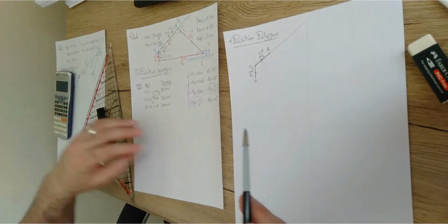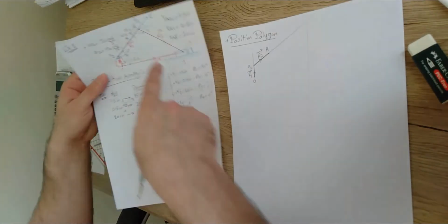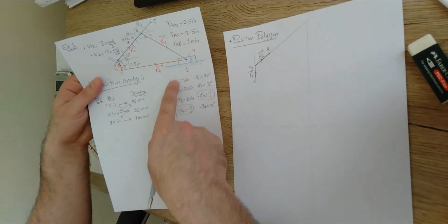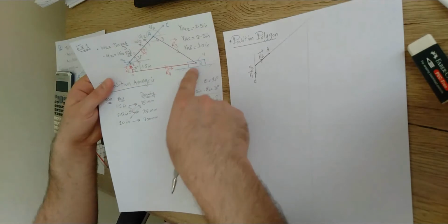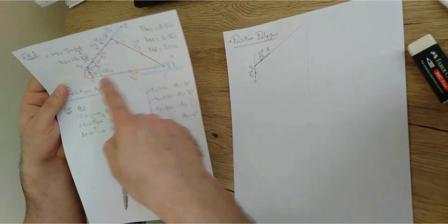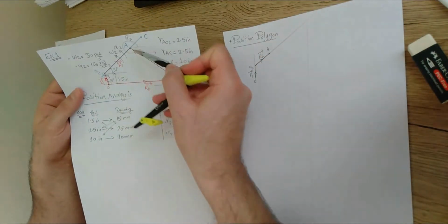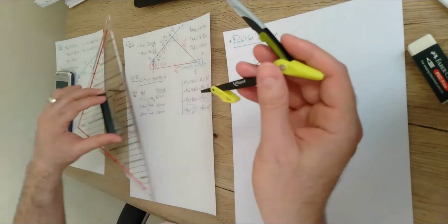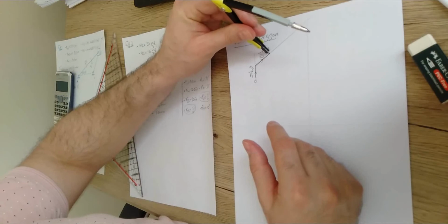Then from either point A or B, because this belongs to the R3 vector, and the R3 vector is set up between points A and B. So in this graph, we have only point A. So from point A, the objective is just to locate point B, because as you can see, we located all the points. We got points O, O2, and A, we're still missing point B, and this is the last point. So using the compass, I'm just gonna fix at point A and draw a curve.